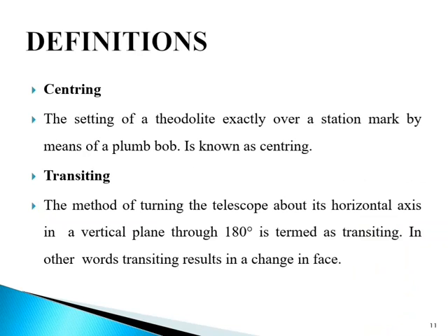Moving forward to some most important definitions which we have to understand before using the theodolite. So you can write down all the definitions. First of all, centering. The setting of a theodolite exactly over a station marked by means of a plumb bob is known as centering.